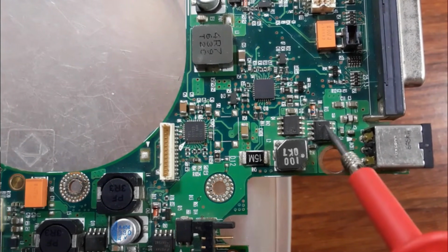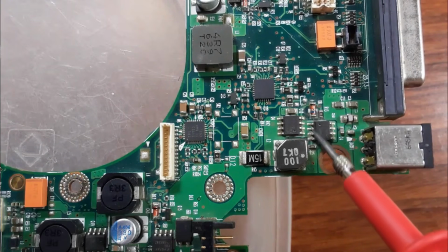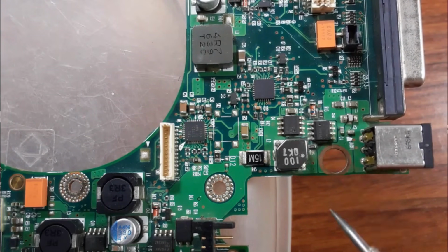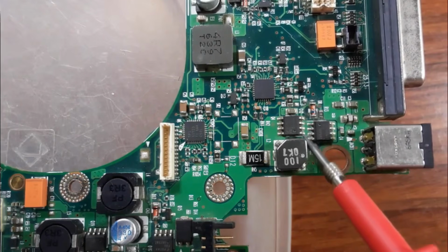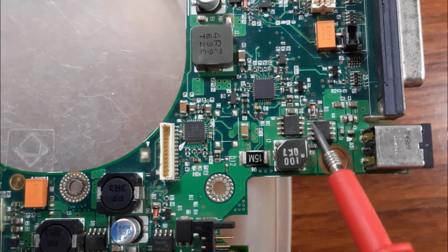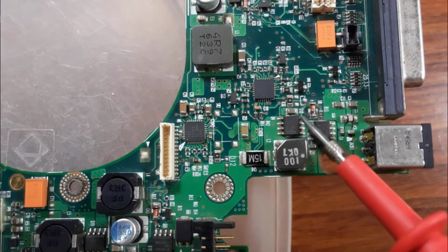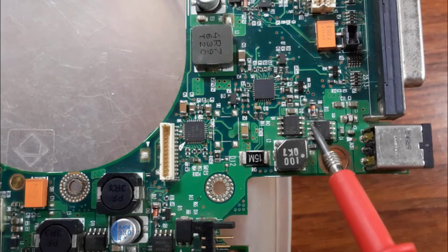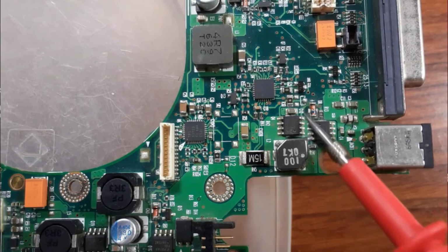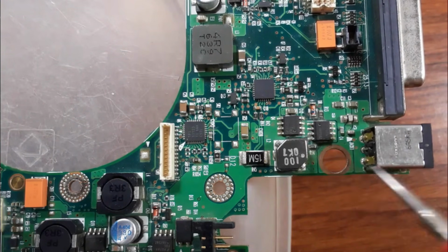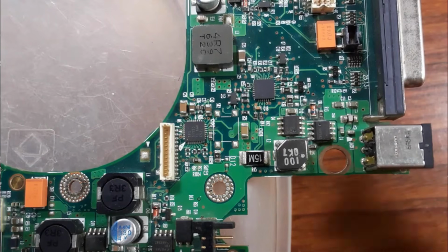If you focus here, for example, this MOSFET is connected to this MOSFET, as you can see. Why? Because here we have the same color. Here we have drain, and also here we have drain. So these 4 pins are connected also to these 4 pins. We can check using the multimeter.